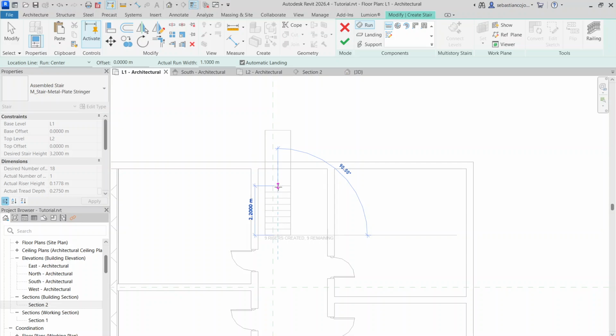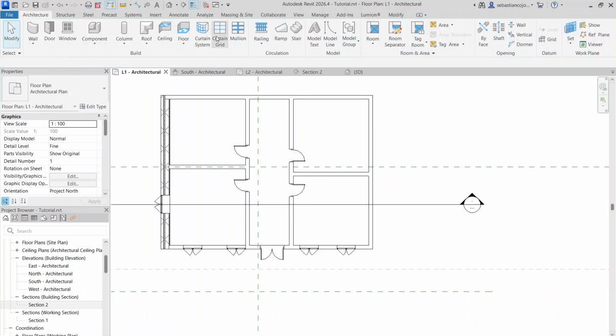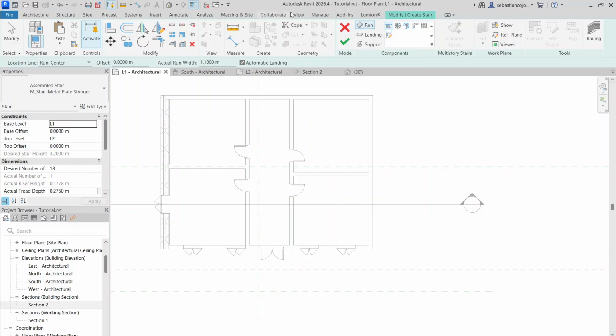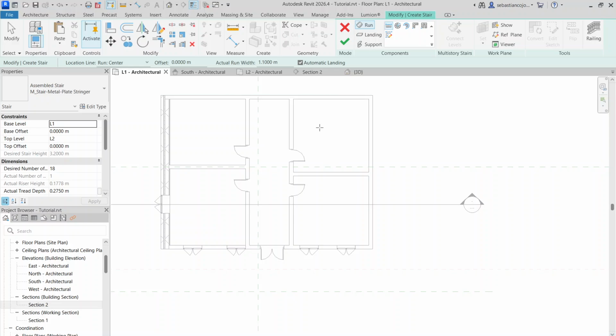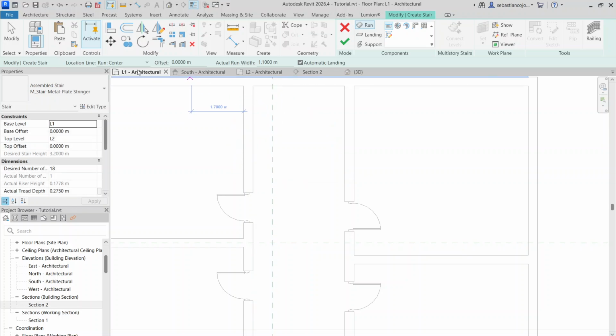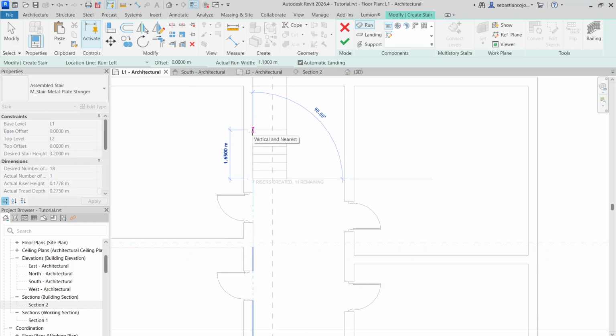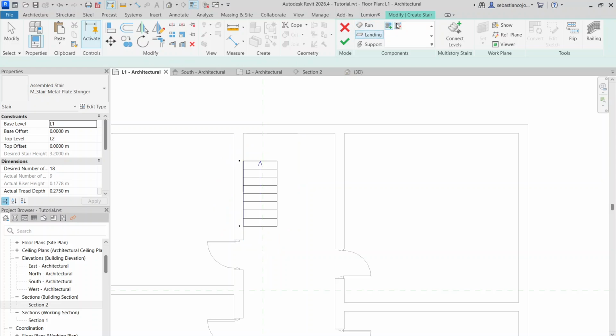So now let's say I can have 9 stairs over here when I create a run, and then another 9. So we will start with architecture stair. You click on that and this menu appears, and now we click run, and we can, let's say, select left, and we basically draw like a wall. Now we have how many risers? Let's put 9 risers.